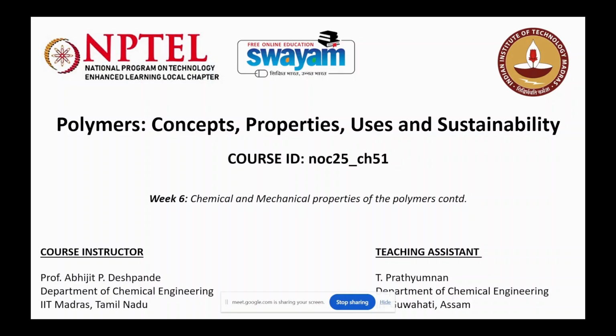So we also discussed that not all polymers which are hard need to be tough. It's a common intuition that hardness and toughness are used as synonyms, but that's not the case when we discuss engineering materials. A material which is hard need not be tough. In case of brittle materials, they were hard but not tough, because the amount of energy that the material stored before it fails is less. Whereas the elastomers are actually flexible, yet they are tough in nature. In case of the ductile materials also, we saw that they can absorb a significant amount of energy. That is predominantly because of the orientation of the macromolecules or the polymer crystals.